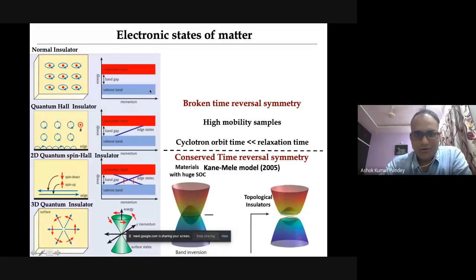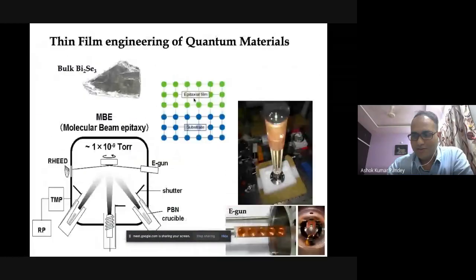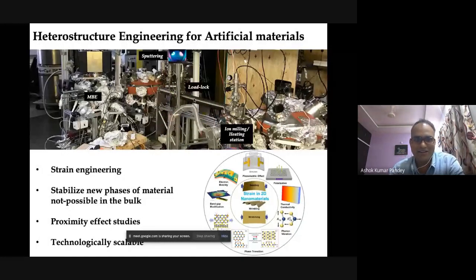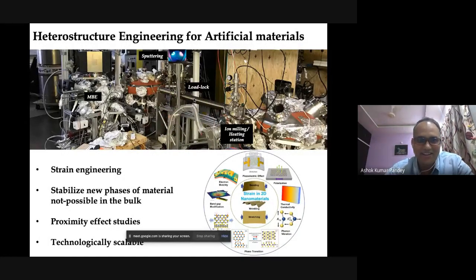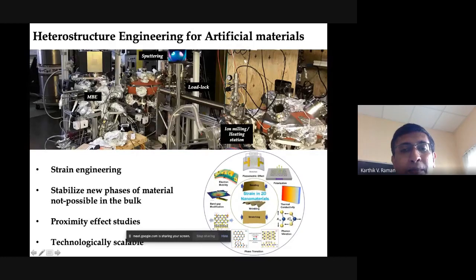And the setup that you showed, everything you mentioned can be done through one chamber, right? Like sputtering, then characterization using TEM and all can be done just by inserting your device in one chamber, right? Yes. So we can, in principle, make the full device stack without exposing it to air. This is important, especially because in silicon technology, you have these clean room fabs where after every step you take it out, you do lithography, then you coat the next element, or you do implantation. That is what we're doing.